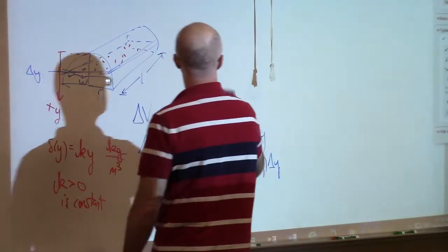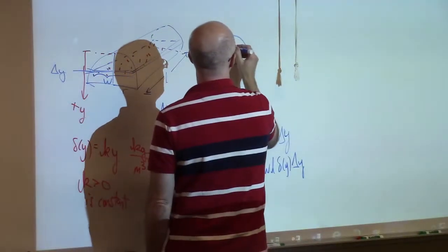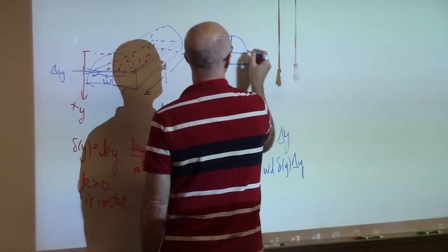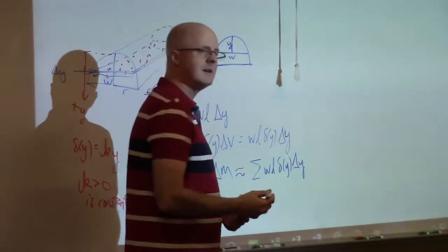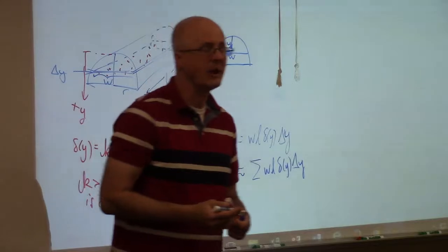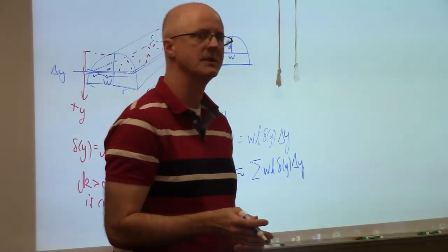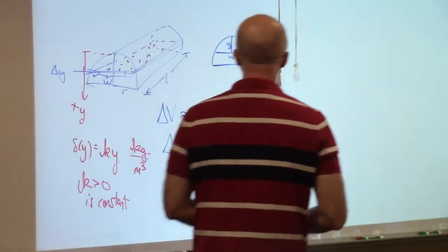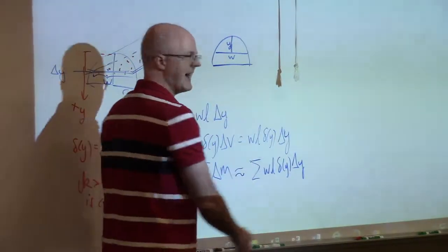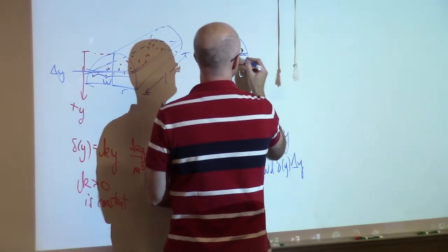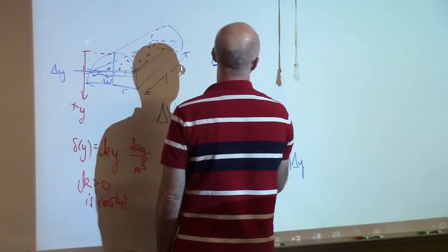You may want to redraw this sort of a head-on cross-sectional look. For a given Y, what is this distance W? You know the formula for the equation of a circle, x squared plus y squared equals r squared when you center it at the origin, and if the radius is r. W over 2 is kind of like an x coordinate. If this entire length is W, this would be W over 2.